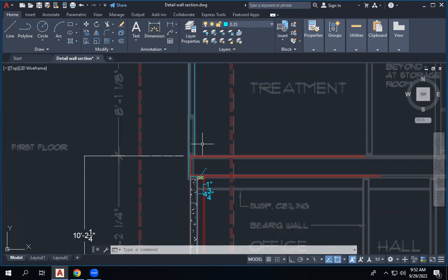There is one thing. Now see, if I stop now, then the actual way is stopping at this point. But can you see there is a difference? This wall is a little bit more onto the left side. So if we stop the truss, what will happen to this wall? It will fall. Yes. So what we can do is move the truss right up to this point where the wall ends on the upper floor. Then we can have this insulation stop here and have another layer start from that point. Because of this situation, most buildings will not have this setback. So if it goes straight up, you will do like this.